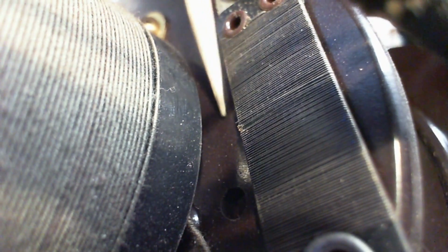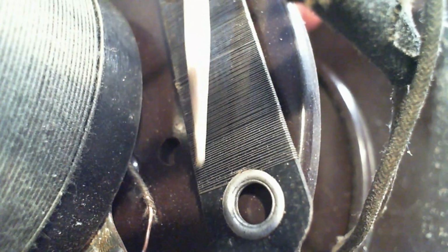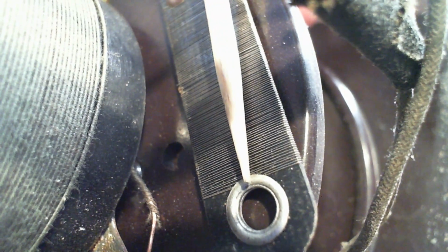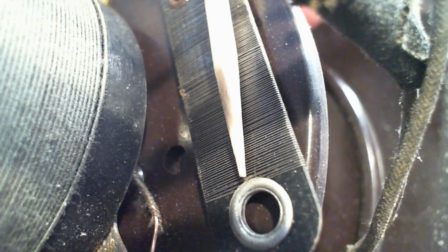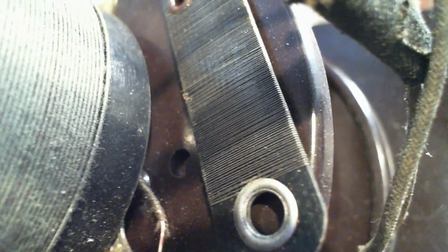Let's just double check and make absolutely sure. Yeah, I'm sure, you can see the end of the wire right there. So it's not likely I can repair that. I could pull a couple turns off and twist them together and whip some solder. Maybe I could. It looks like there might be a bit of a problem right up in this area too. Anywhere you see some rust, like right up in, ooh, these wires are so fine. So is that the connection? They just slammed this rivet down on the wire? The other end? How do they do the other end?